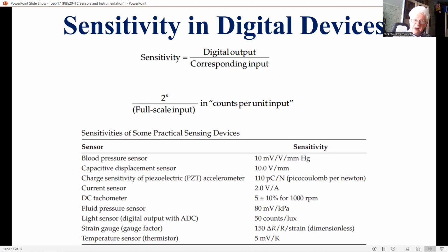An n-bit device can represent 2^n values, including 0. Then the maximum possible value for unsigned is 2^n minus 1. To represent signed values, we need to assign one bit as a sign bit. And then an n-bit device can represent 2^(n-1) minus 1 positive values, including 0, and the same number of corresponding negative values, right?